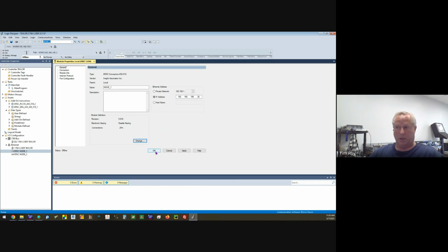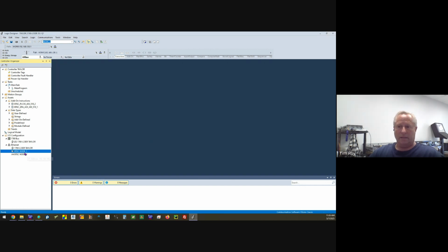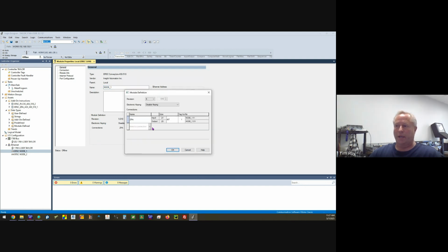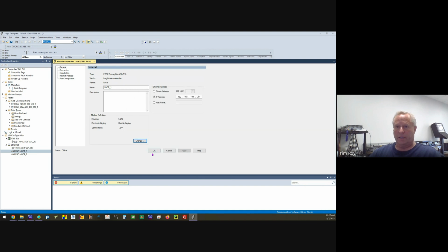Now you can press OK here. If you forgot, let's say you pressed OK and it closed. Oh, wait a minute. I forgot to change this to an integer. Then you go back and do it after pressing this OK. It won't work. You'll have to actually delete this module and then recreate it.